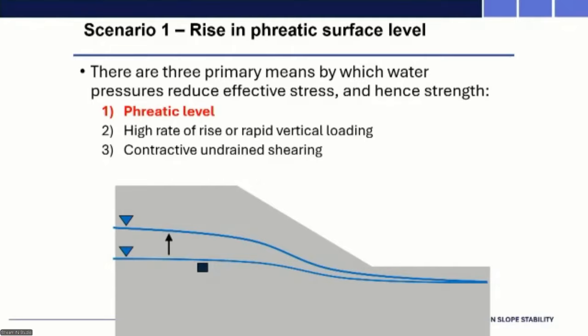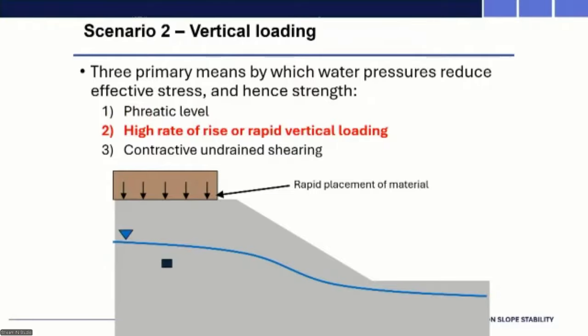So that's mechanism 1. Now, maybe that's in isolation. The second one is one we're again kind of familiar with, and maybe think about when we think about rate of rise calculations in TSFs. That's where we're applying essentially an increase in vertical stress. So that element of tailings is still the same depth below the phreatic surface, the phreatic surface probably not responding to the load, but there's this rapid increase in total stress, which the element of tailings reciprocates by an increase in pore pressure, which therefore affects your effective stress and hence your strength.